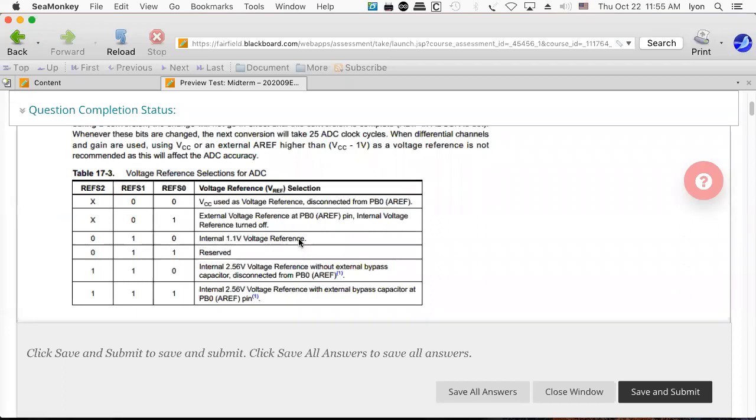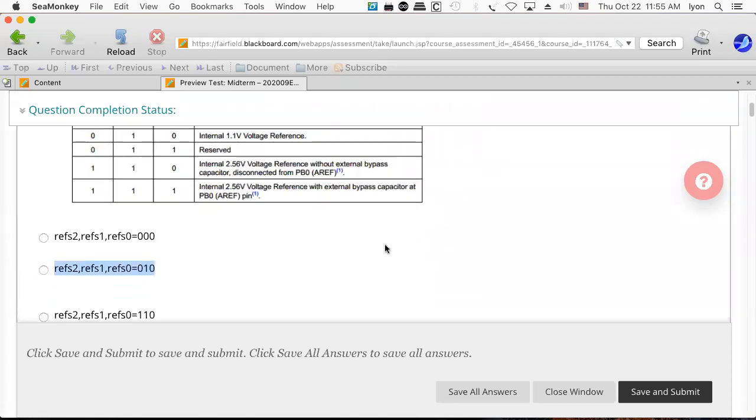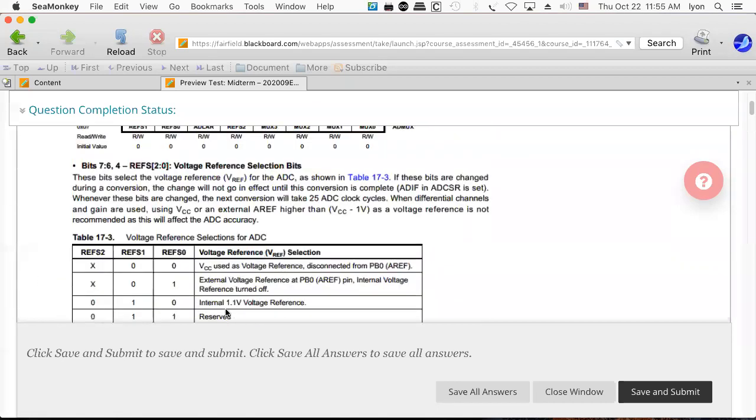So that's kind of convenient, right? Because maybe you would like to have a high sensitivity input because what you've got is a relatively low output, perhaps from a microphone or a guitar or something like this. Guitars are usually 1 volt peak to peak, maybe less, probably less. Well, actually, guitars without any preamp will be in the millivolt range.